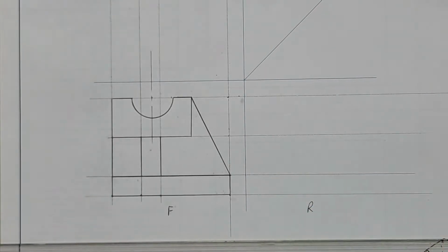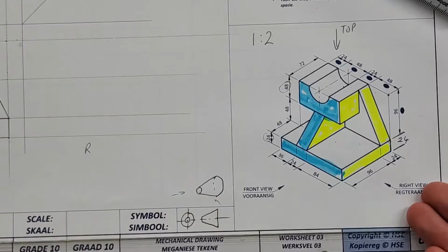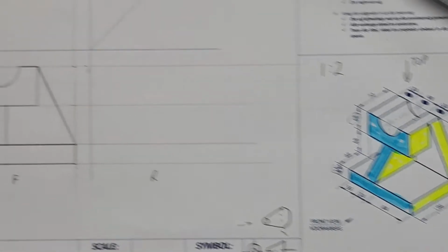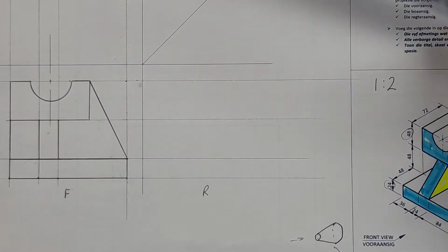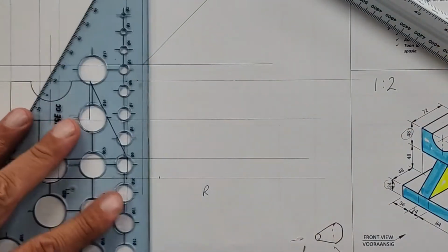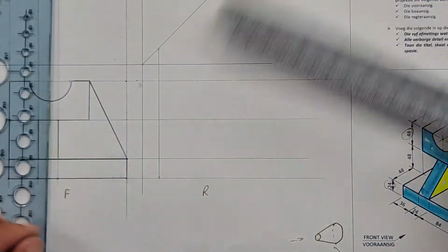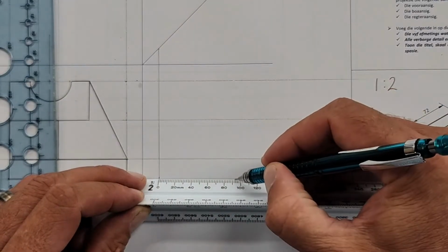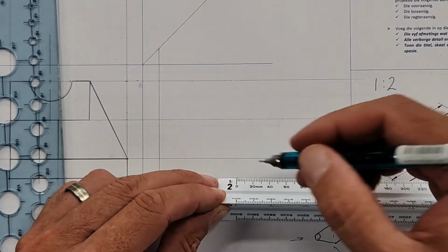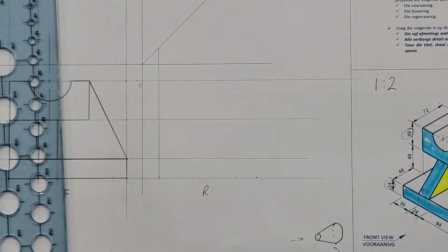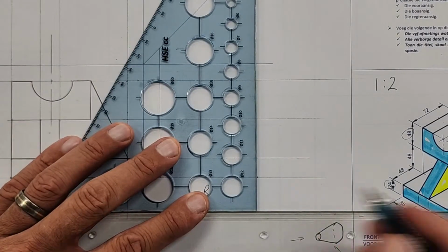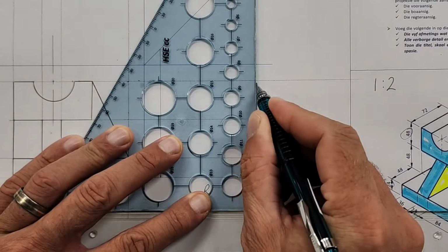Alright, so let me do the right view. So the right view is next to it. Now we're looking from this end. Now we're using this width, the 96 and the 24 on this end. So again, first your 10 millimeters. Just draw that up to there. Then we have our 96. And then we have another 24 next to that. Okay, so let's start there. So this one on the side goes all the way up here.